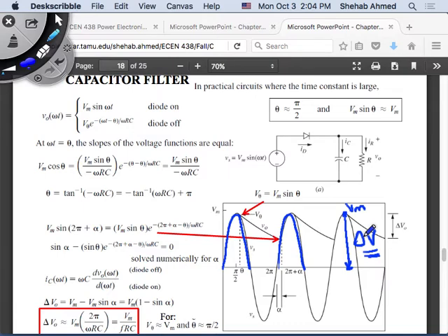So 10% of the 3.7 volts is your delta V. Half of it is on top of 3.7. Let's say 3.7 is your ideal value. So you're accepting a delta V of 10%. So this is delta V equals 0.1 times 3.7. That is your ripple. That's what you will accept.